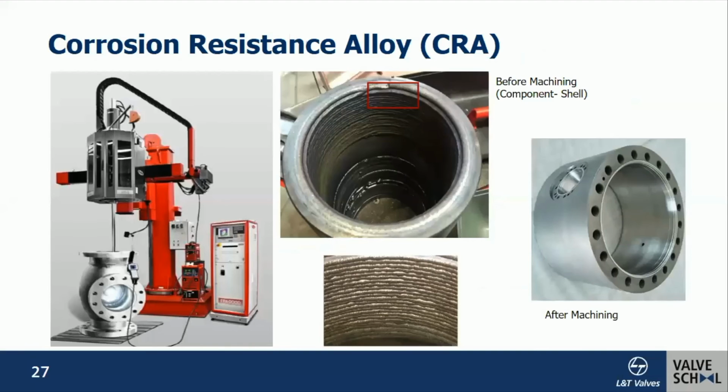The valves with special designs can also be provided with the Inconel overlay on wetted parts of the body and the connector. These primarily go in for applications involving the presence of hydrogen sulfide, or sour service applications, where these special requirements can be taken up for any size and pressure rating. The body and connector are provided with this overlaid Inconel 625 material, and in addition to that, the internals like the ball could also be provided with this overlay, whereas the other smaller components would be provided in the corrosion resistant material itself.